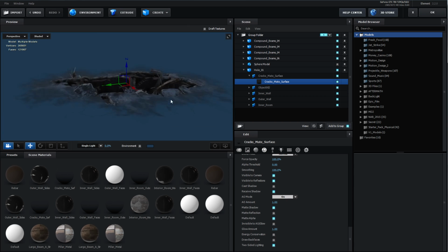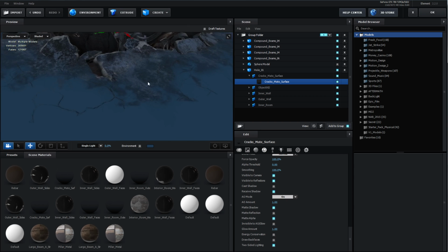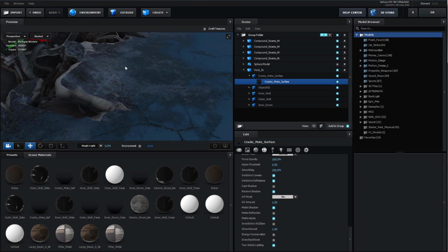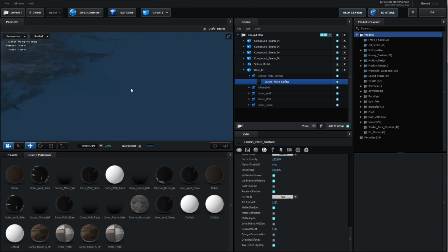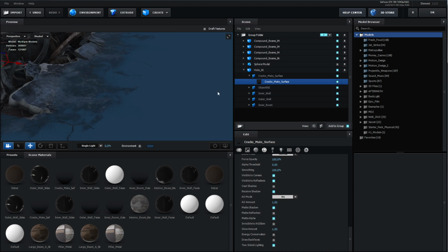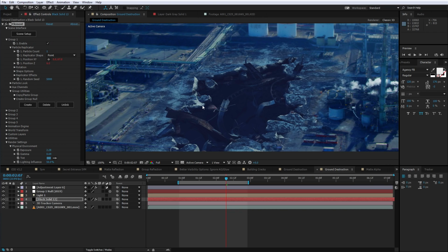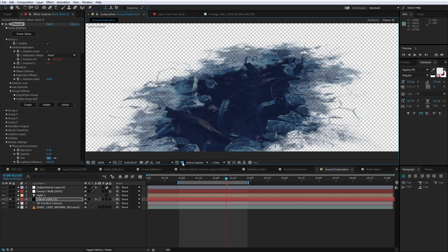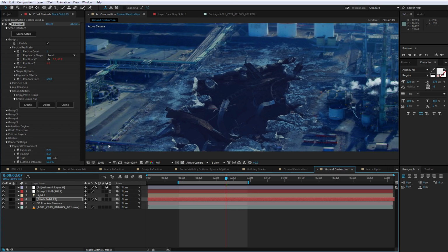And what that does is adds the alpha channel from your PNG into your scene. So check this out. You can see it fades out from being opaque to semi-transparent all the way off. So if I hit OK, so now you can see I have a nice gradual fading texture that blends over my live action footage. You can see what that looks like.